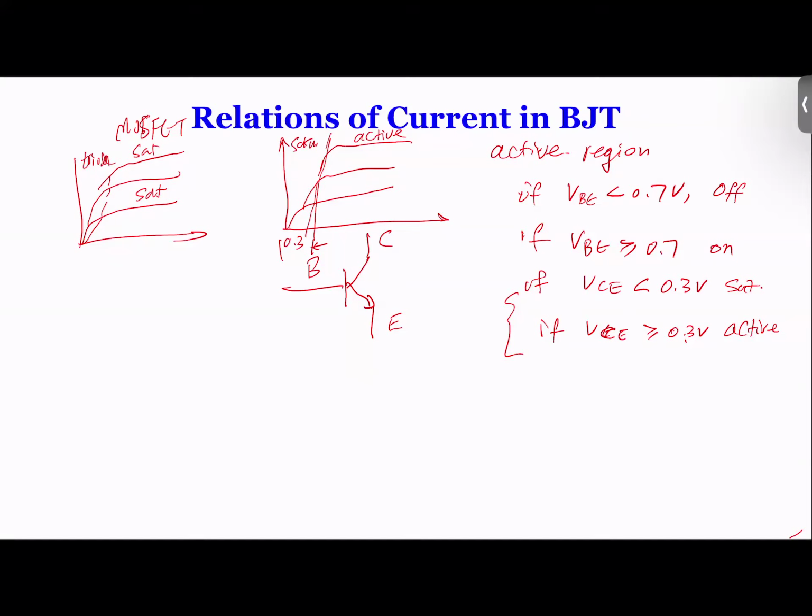But of course, in this particular class, you need to know whether it's in off mode, on mode, saturation mode, or active mode. If I give you a circuit, you do some calculation, and you can tell whether it's in the off state, the saturation state, or the active state. Even though the active state is what we want, we still need to understand how to design the transistor so that it is in that mode.